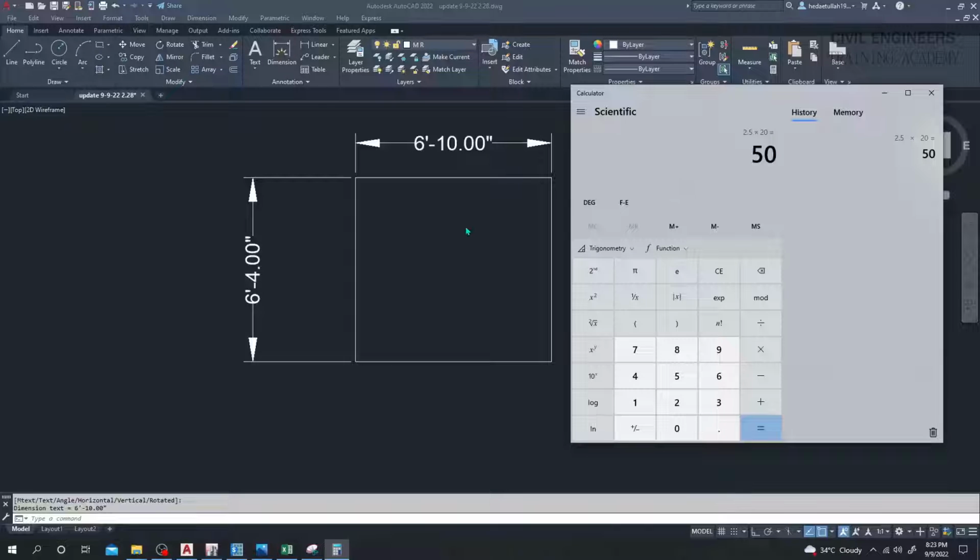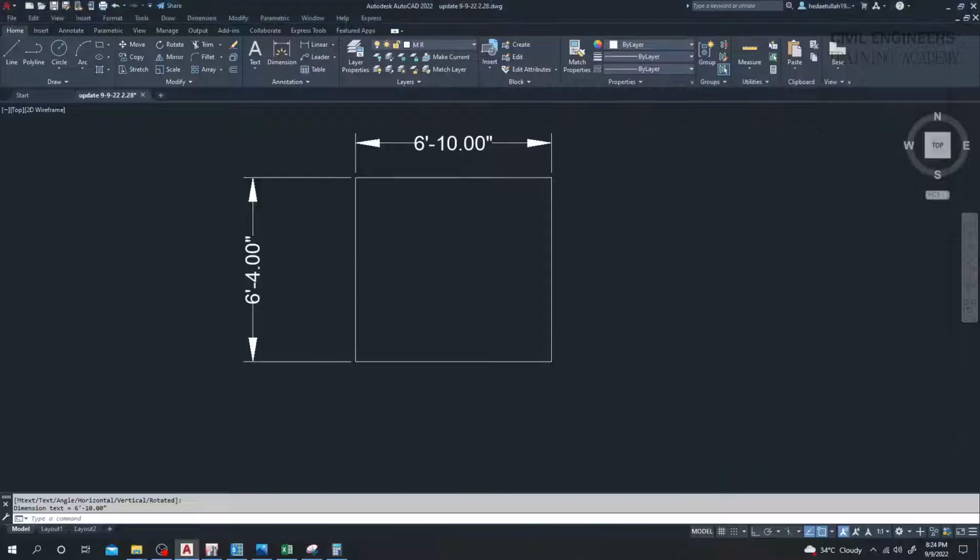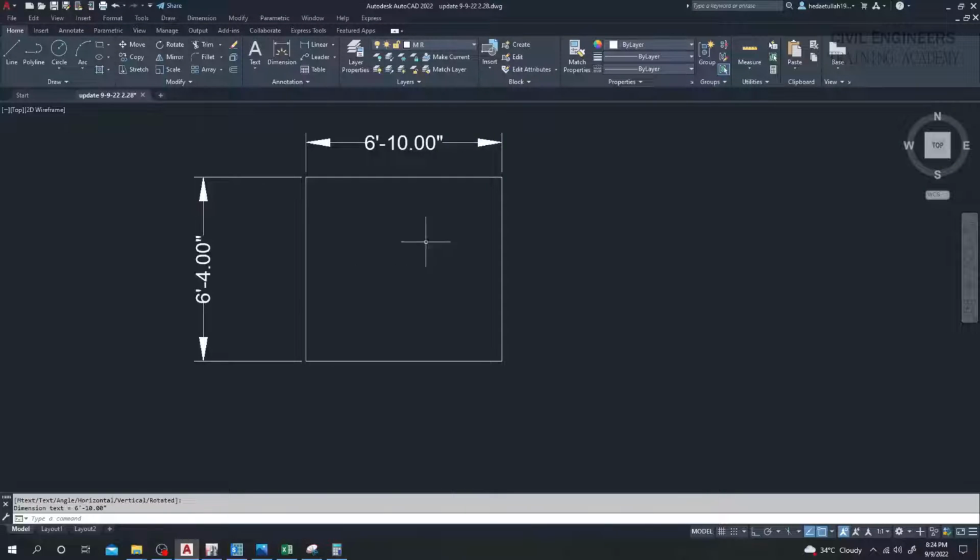2.5D means diameter of pile, that means 20 inch, that means 50. And another thing we have to do here, so one pile to another pile distance will be 50 inch, right? Now in that direction, what is the value of 50 inch divided by 12? That means 4.16 feet from the center to center value. So here in middle position we'll provide 2 piles and 4 piles in 4 corners.